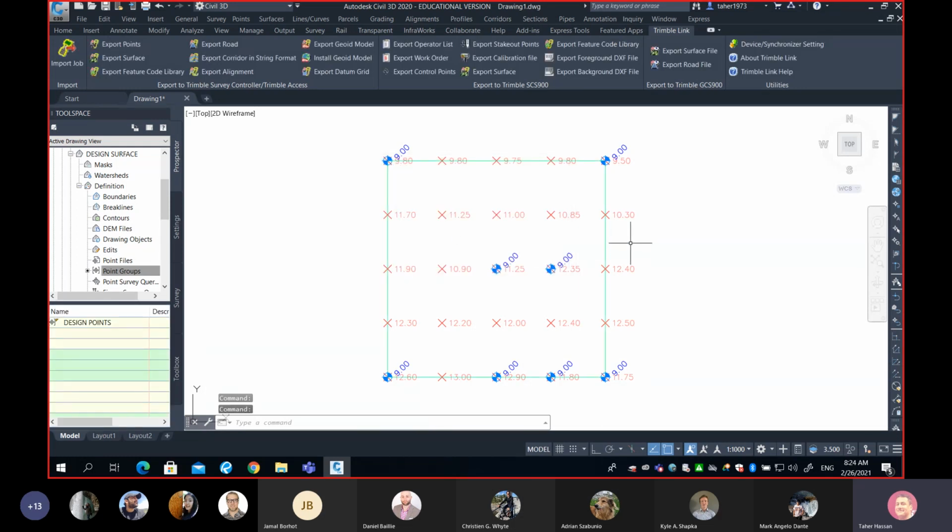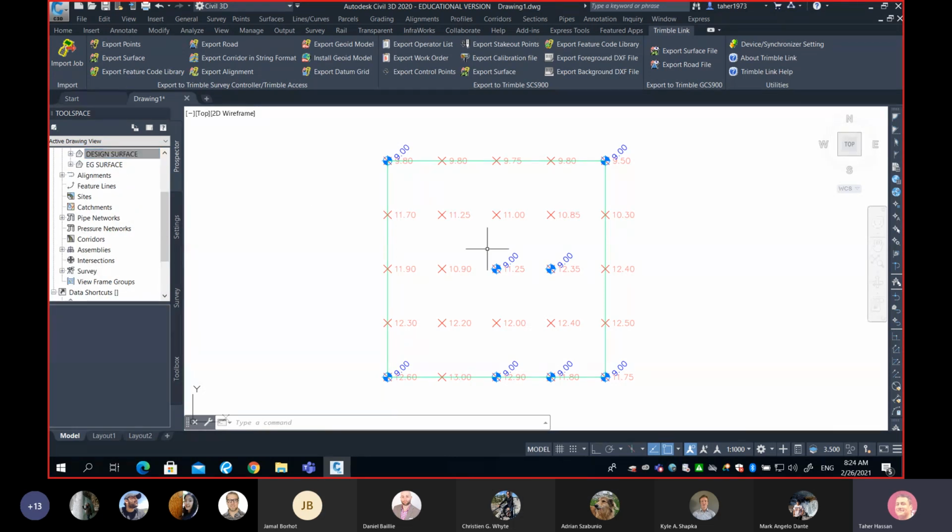Now you can see my surface is built. We have the green outline, or the boundary, of my design. But you know that in general, when I do that, I get some contour lines. Can anybody tell me why I don't have any contour lines right now? Because we have contours of 2 and 10 meters, and we are not past 2 meters. So you think if I change my contour interval to 1 centimeter, you'd see more contour lines? No, sir, that's not right.